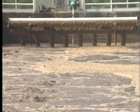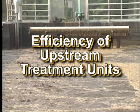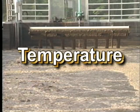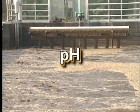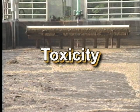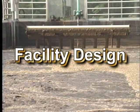Remember that factors that impact nitrification, once again, are efficiency of upstream treatment units and processes, dissolved oxygen, temperature, mean cell residence time, alkalinity, pH, CBOD removal, toxic compounds, wet weather operations, and facility design.